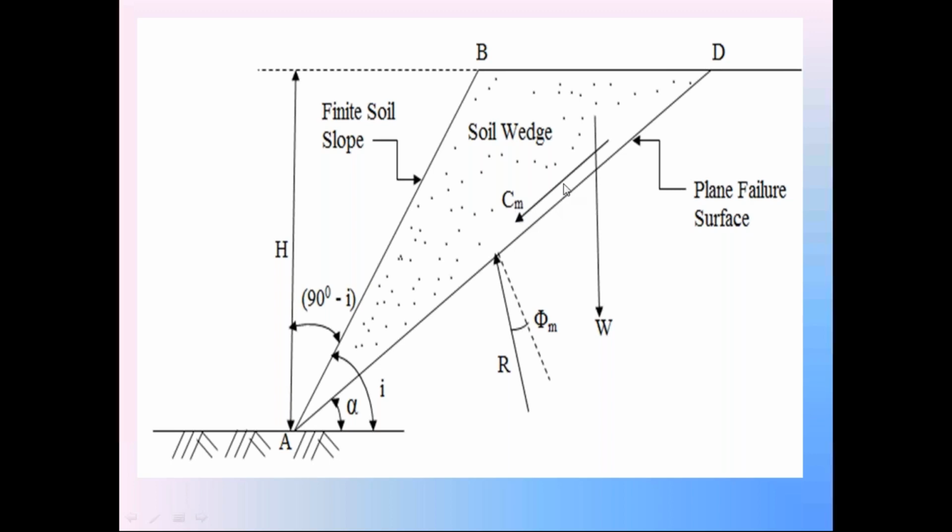So here you have this sign CM. Check the direction downwards. It indicates the failure condition of this side wedge. If this side slope AB is subjected to failure on the surface AD, at the instant of failure, the cohesion in this side wedge is called mobilized cohesion, CM. Since the side wedge is moving in downward direction, this mobilized cohesion is also moving in downward direction.